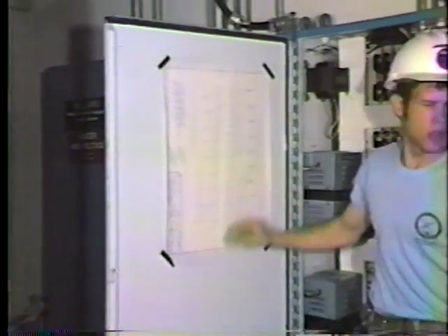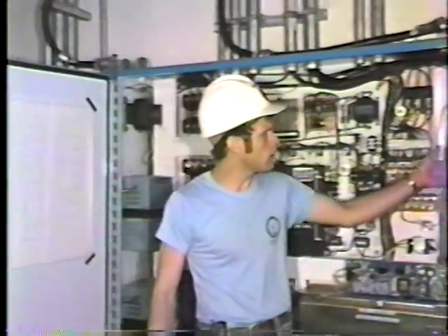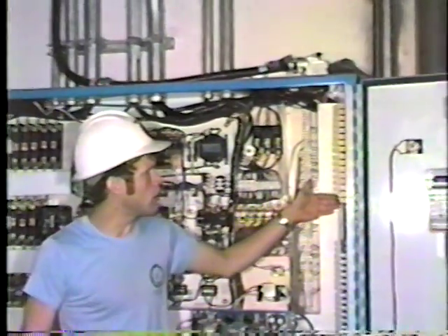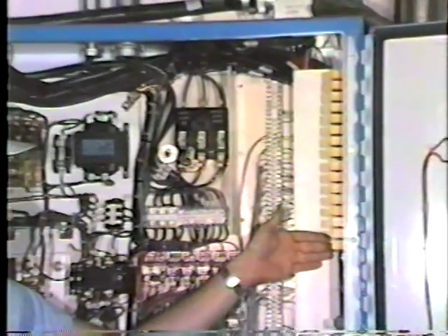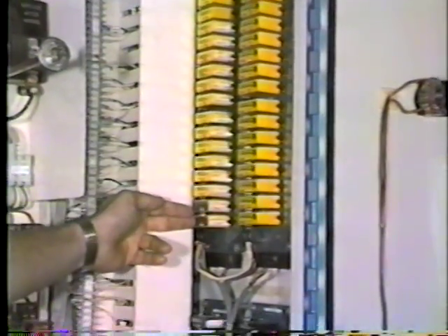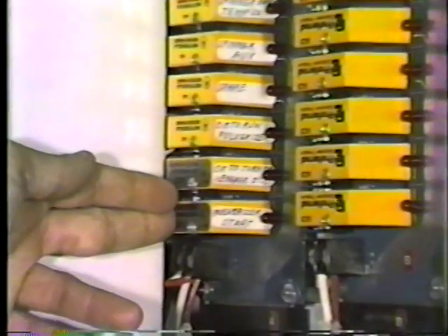Those are all inputs on that sheet? These are all inputs. Show me where the inputs are. In the cabinet, the inputs are located on the top rack inside. The first input is pulverizer start. The second input is okay to turn on and engage the eddy current clutch.